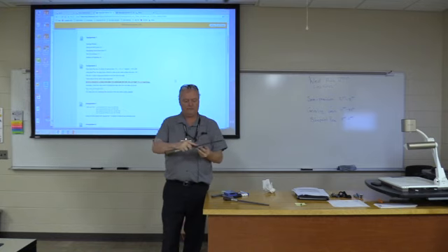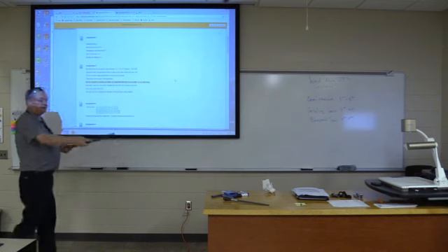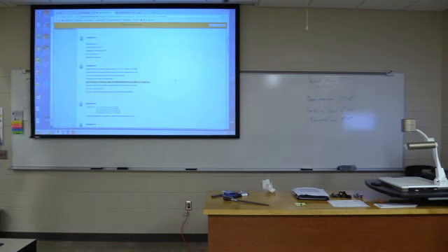Again, this file can be used like so, with both hands on it. Nice strokes are better. So those are the two surfaces. And the way you inspect it is you just take that steel square and put it up against your part. Now these files are perfectly flat, so if you stroke with them flat, they'll do a good job for you. What we don't want to see is you coming off the edge, just nice and flat.